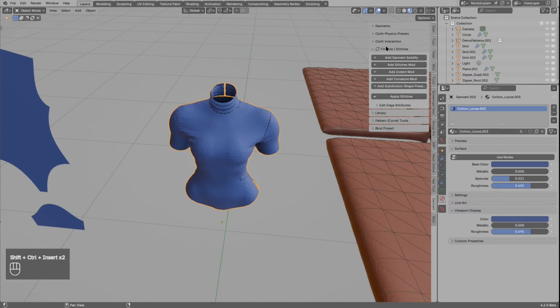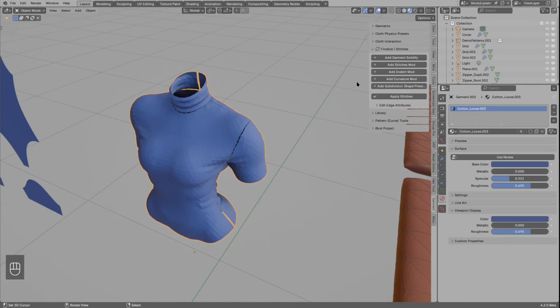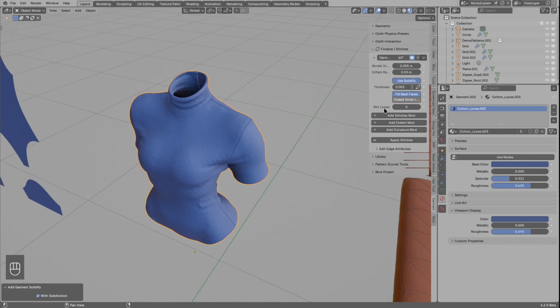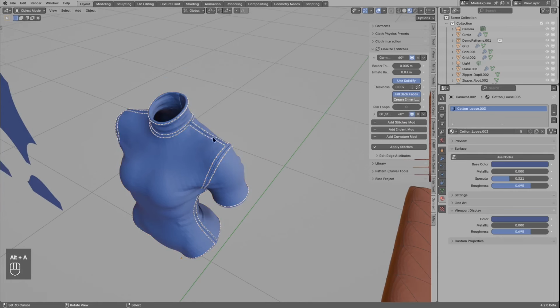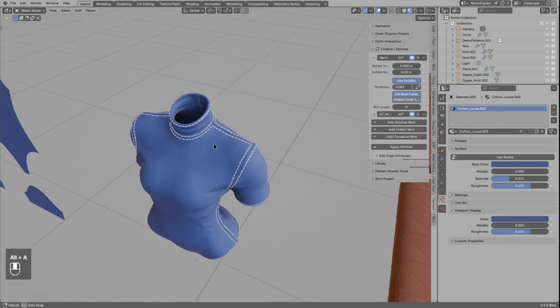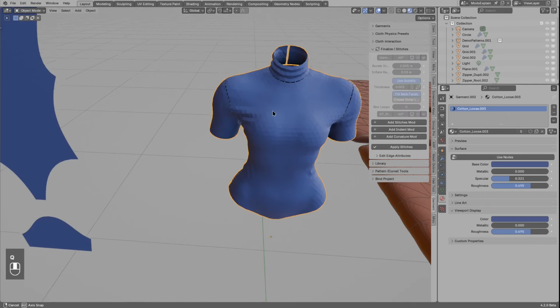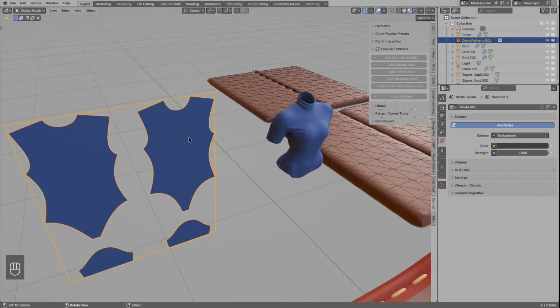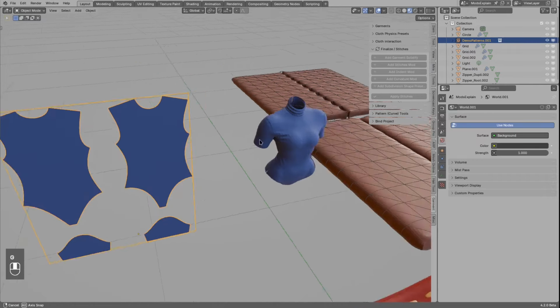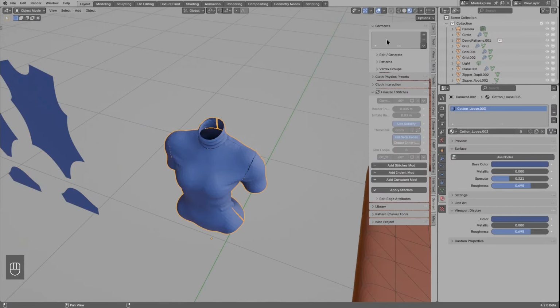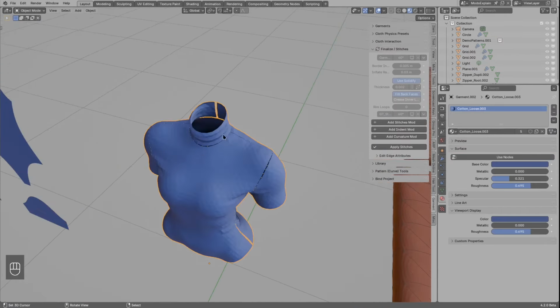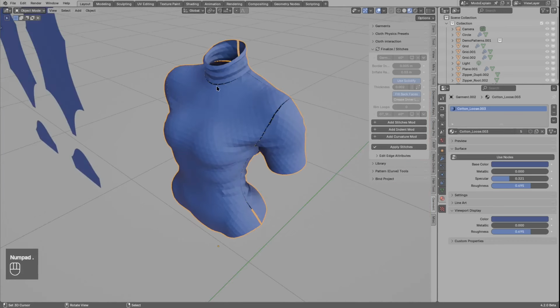Now I will jump to the panel Finalize Stitches. What this does is add the Solidify modifier, the stitches, and you are basically done. Now let's go over the setup. I will remove the modifiers, and you would want to simulate the sewing patterns, and then in the garment tool, press Finalize to bake the cloth sim into the mesh.